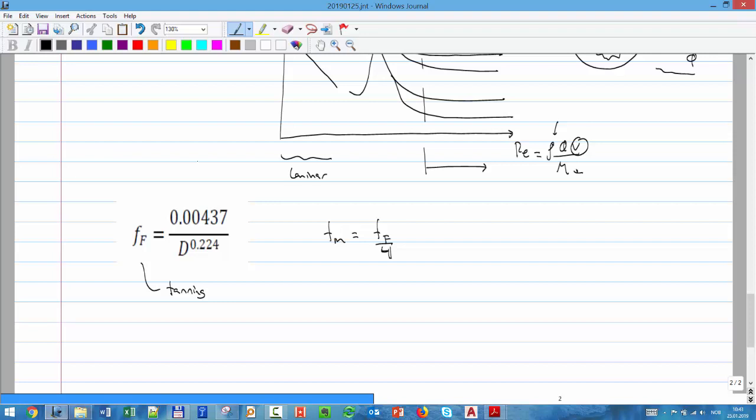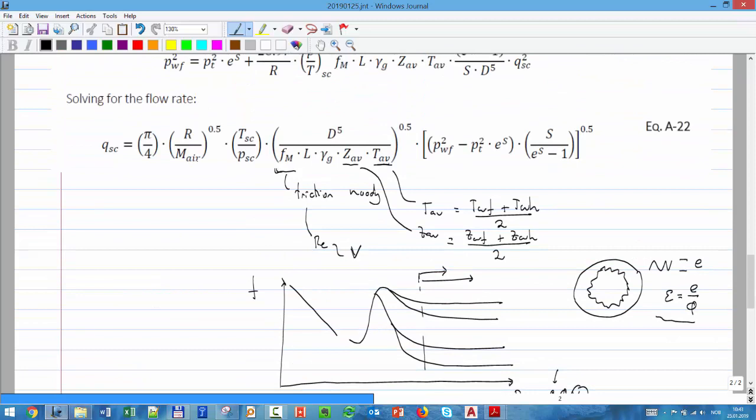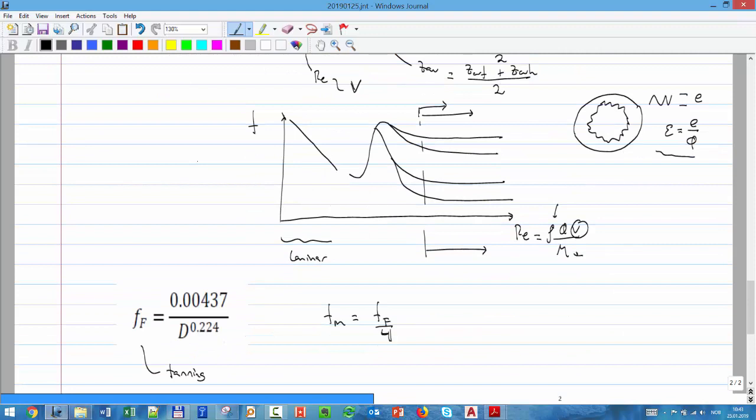And voila. That means that friction factor, that Fm that I had here, that in principle I had to say, well, it's going to change because the velocity changed. I'm saying gas is always in the fully turbulent regime. Therefore, it's only a function of roughness. Roughness is a function of diameter. Finish. And that makes it much, much simpler.